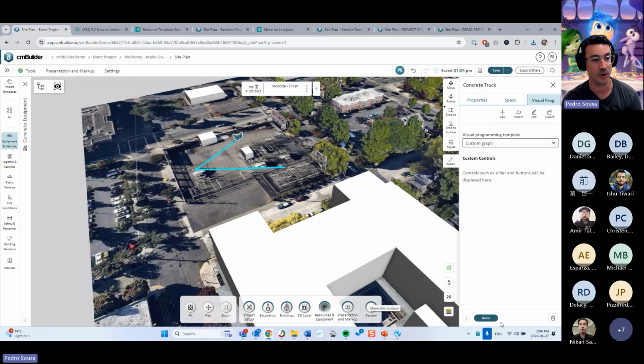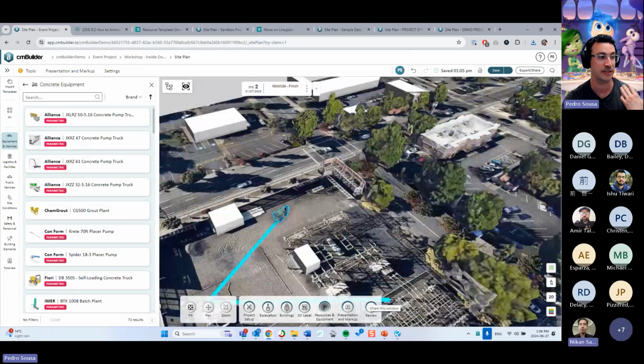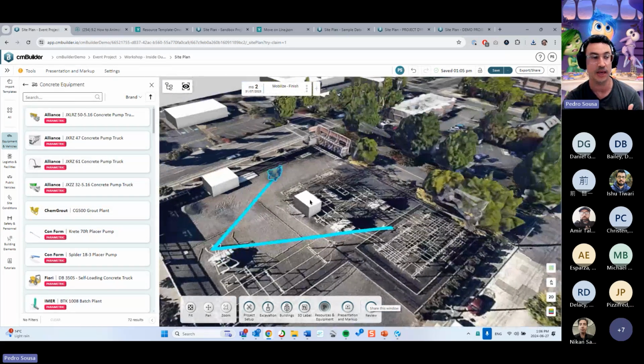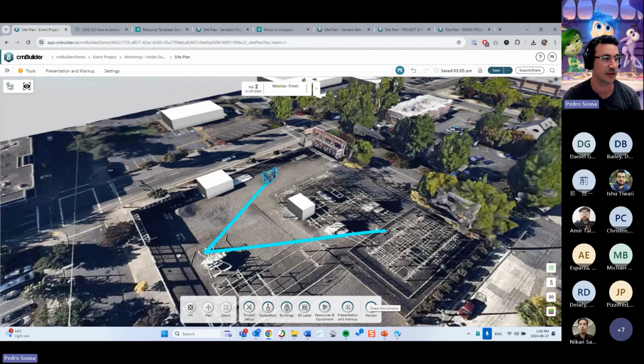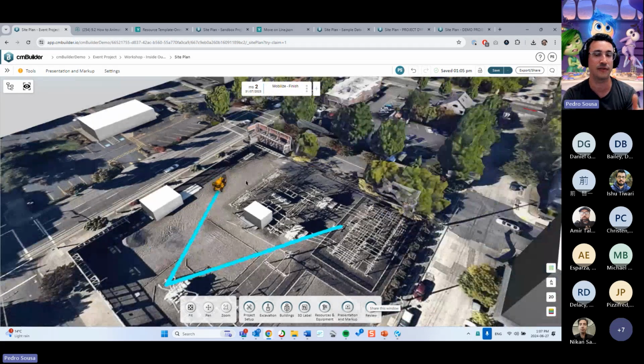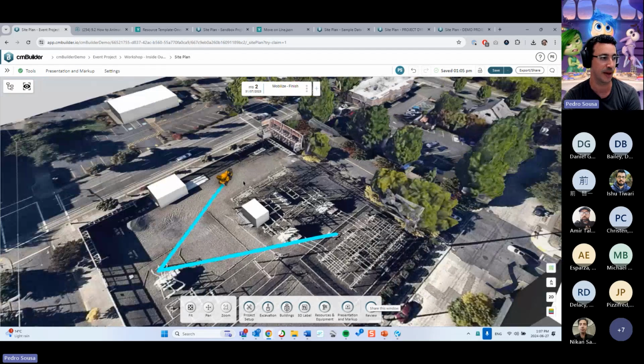In the meantime, what you can do is, every time you duplicate an excavation, create a little offset, like I mentioned before, a millimeter or an inch, or half an inch, just to prevent it from having coplanar faces. Coplanar faces are the issue that we are solving at the moment. But every time you duplicate it, if you offset it by a little bit, it will prevent that issue from happening again.